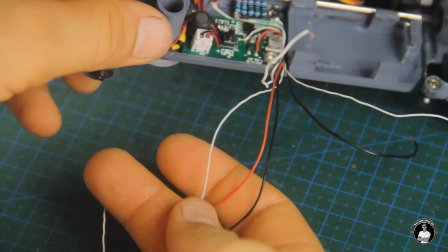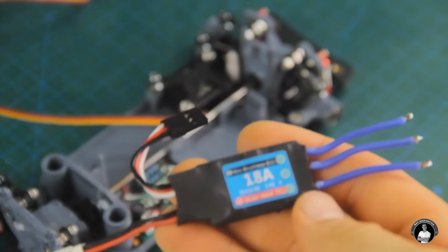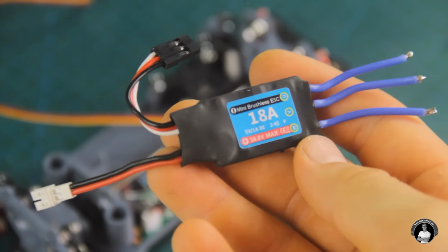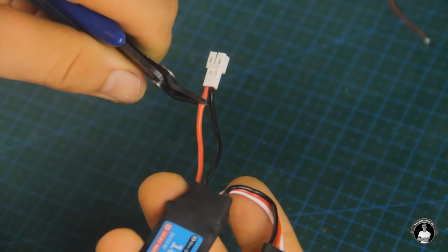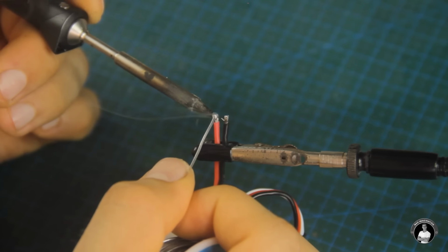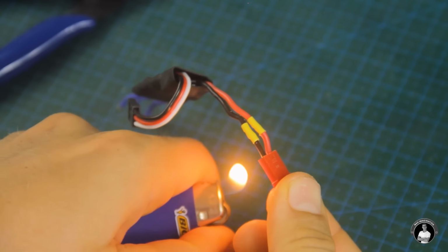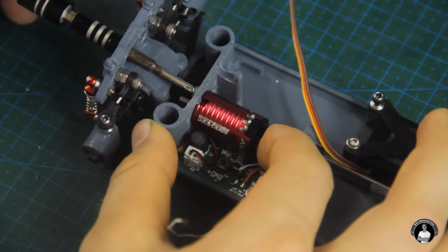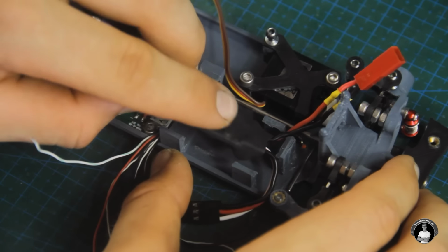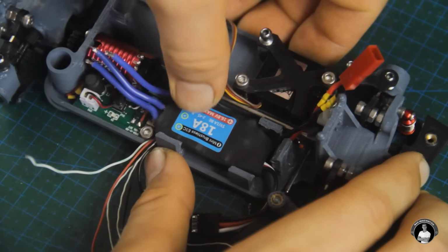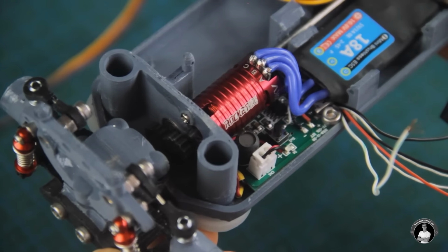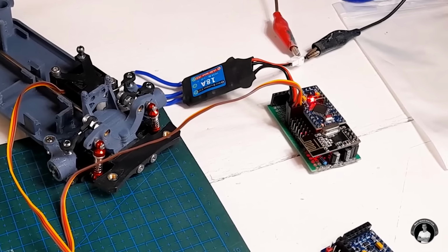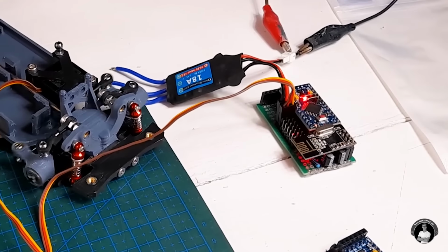the humidifier's power module. To control the motor, we'll need a bidirectional brushless ESC that can handle 18 amps, or double the current output of the installed motor. We'll simply need to replace its power connector to instead match the one on the battery and then pop it into the chassis where it's designed to sit. Then we'll solder the 3 wires in order to the motor's terminals. The outer 2 can actually be swapped to reverse the motor's rotation. Electronically, all we really need now is the receiver.